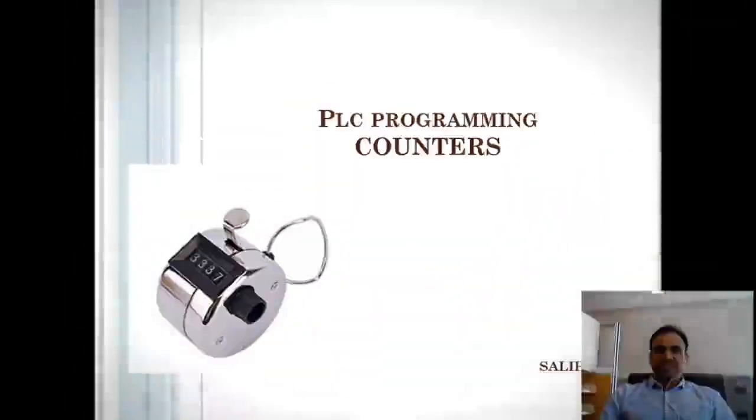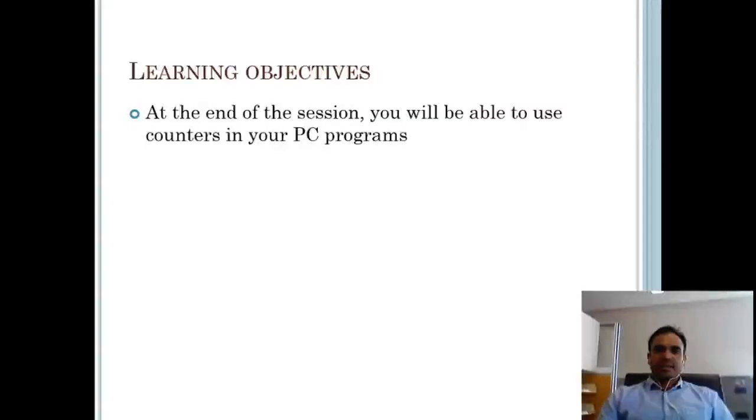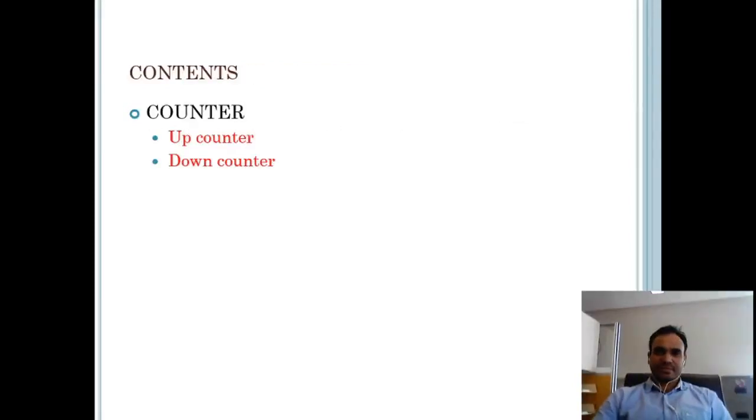In this session, we will discuss counters. At the end of this session, you will be able to use counters in your PLC programs. In Logix Pro software, there are two types of counters available: up counter and down counter.